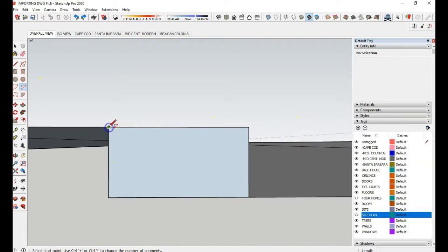And you're going to start here at the top of the curb. And generally in this area here, you can pick and it'll form this. So you don't want to go outside like this. So once the left side of the curve here is pretty much even at the top of the sidewalk, go ahead and pick there. Now this other part, if you remember, we need to see the cyan color line in order to have a good transition in this area. So if you just come down here to the bottom of the street, that's a good pick.